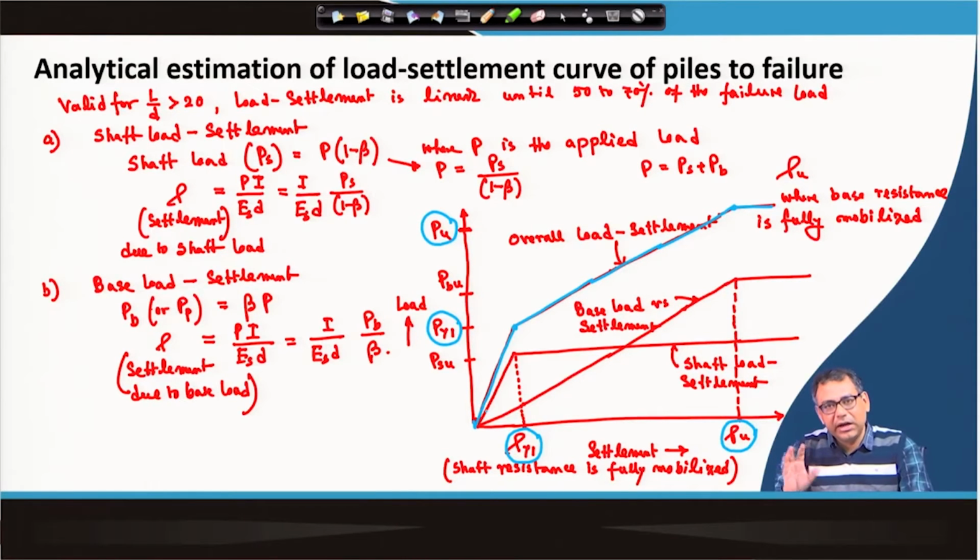So, that will not create any effect on the settlement of the pile material, but it will affect the settlement of the soil. The settlement of the pile material will be due to the load which is transferred to the tip of the pile or the base of the pile.